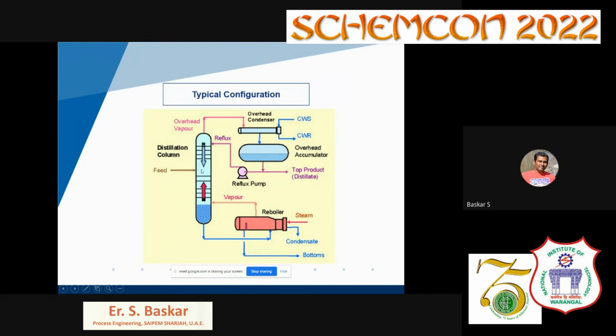In the same way, the liquid that entered the distillation column will travel towards the bottom of the column, but the vapor coming out of the reboiler will be at a higher temperature. This higher temperature vapor will boil up the lighter components, meaning those with a low boiling point. It will vaporize the lighter components in the liquid and take them along with the vapor, and the light components will travel towards the top of the column, where they will be condensed in the condenser.